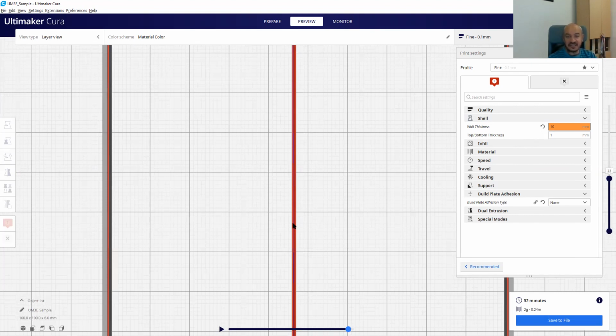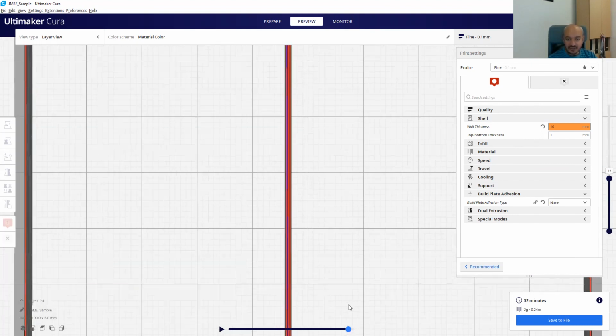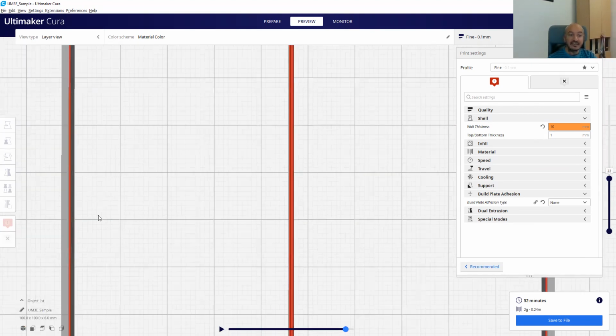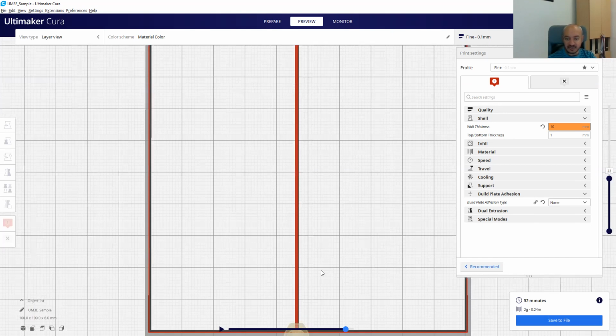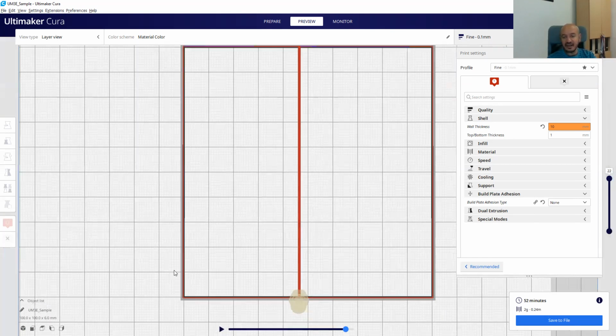But obviously at the center, since the thickness is a bit higher, as far as I remember, 1 millimeter, that's why we have 3, as you see, or I'm not sure. Yeah, we have 3 shells, but for the left, right, and top and bottom sides, we only have a single shell. And I'm repeating again, since the thickness is equal to 0.4. That's how I designed this model in CAD software and then saved it as an STL file and later imported it into this Cura software.